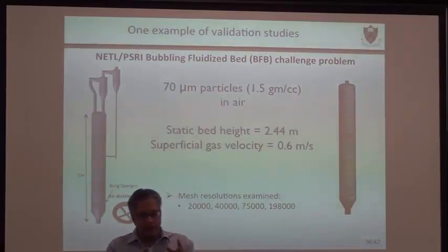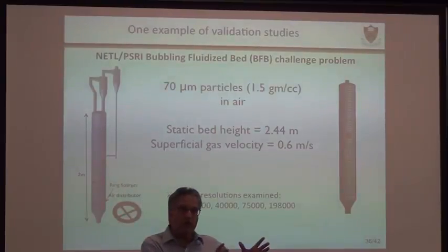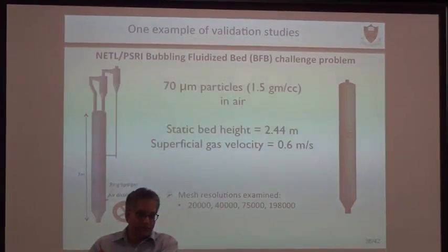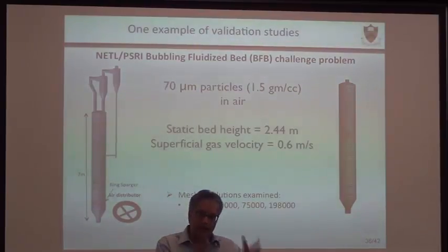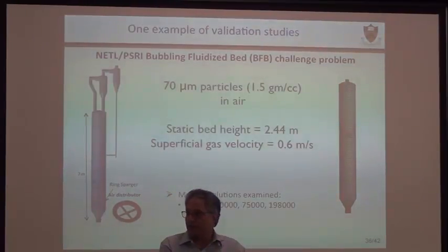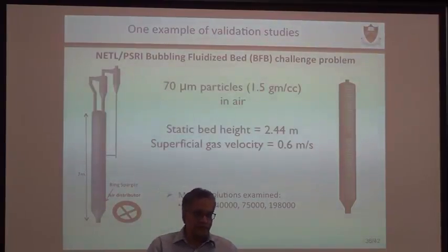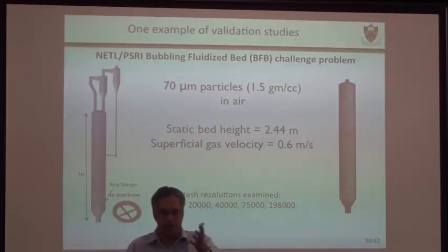One of them is that we have to verify this model as one element. So we take this constitutive model, put it into our two-fluid equations, coarse-graining two-fluid equations, and simulate them. We get a certain set of results. Then we take some small-scale test problems, put lots and lots of grids so we can resolve all of these problems, and get the analog of direct numerical simulation. So we say that the coarse model should give the same coarse result that you obtain from a fine-scale simulation. We do that first to make sure that our coarse model is faithful to the fine-scale data on which the coarse model was built.